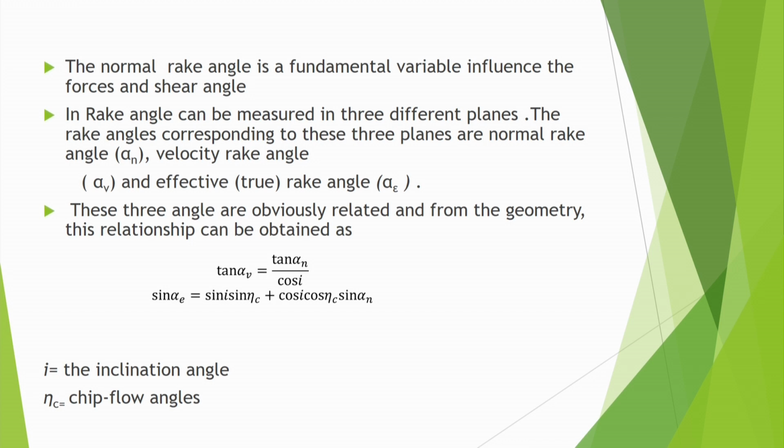Here it is stated that to apply to oblique cutting the results of the large amount of orthogonal cutting data available, it is necessary to select a rake angle in oblique cutting which corresponds to the unique rake angle of orthogonal cutting.